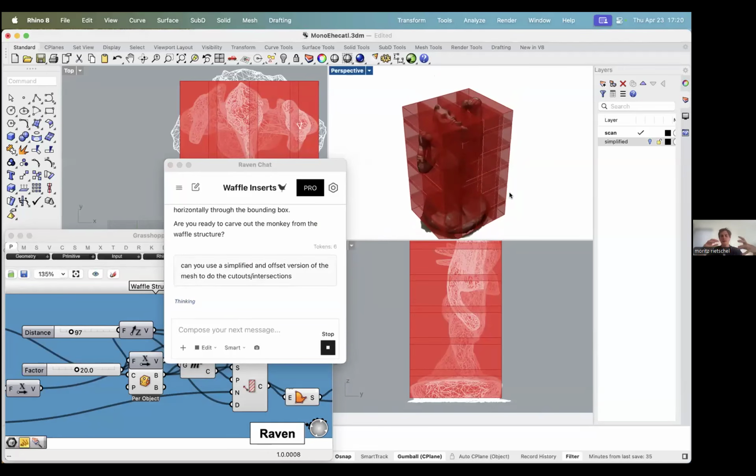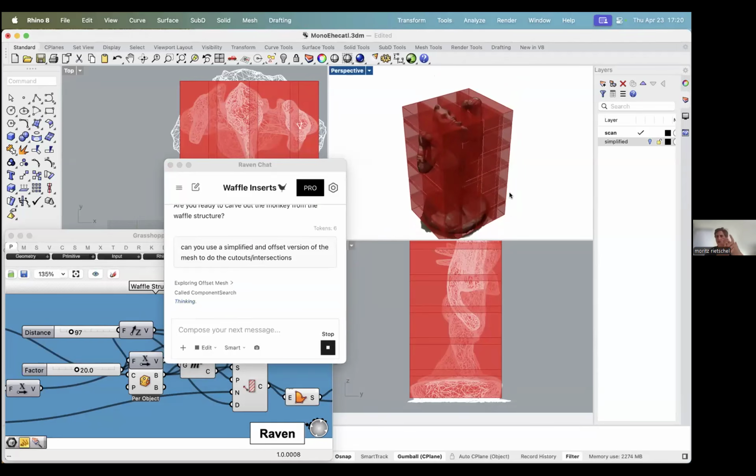And you can see that going for one geometry with the idea, and I have my 20 millimeter foam boards, I can use Grasshopper for so much of that process to find the bounding box, to define my foam boards, to cut out the pieces of the mesh, all the way to maybe a laser file that I can send to a machine that cuts them for me. And then I don't just have this one result, but I actually have kind of a pipeline. I have a script that does this logic that I've worked out in a session with Raven. Next time I want to do something like this, I can open the same script up again, jump into Raven and have it modified. And that's actually true for all Grasshopper files.